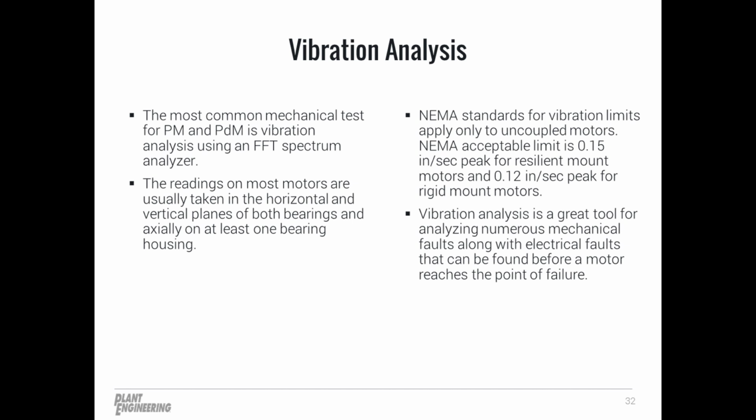Vibration analysis is the most common mechanical test for preventive or predictive maintenance. This test is performed by using an FFT spectrum analyzer and using an accelerometer that is usually placed in the horizontal and vertical planes of both bearings and actually on at least one of the bearing housings.